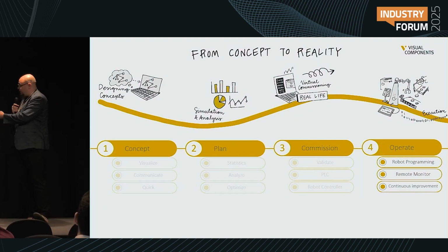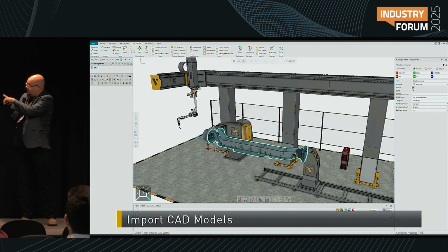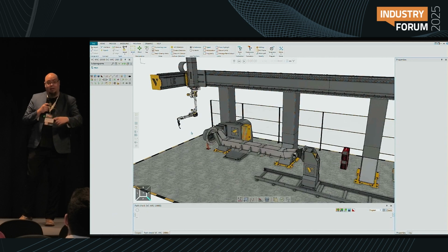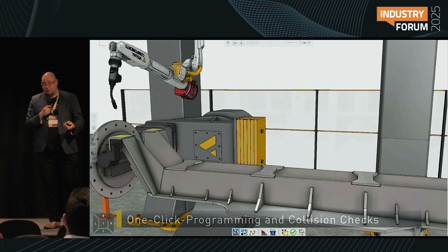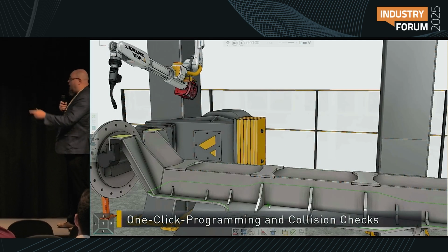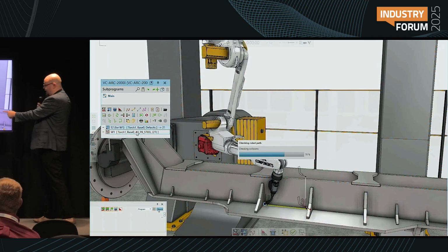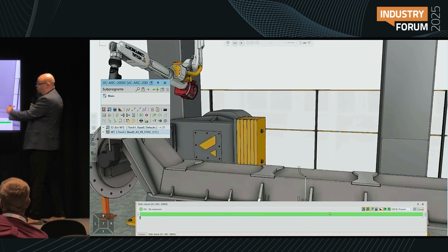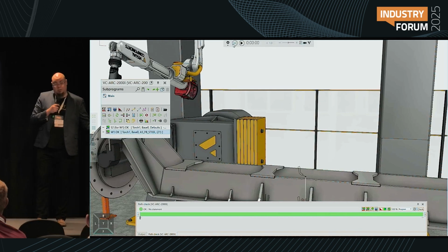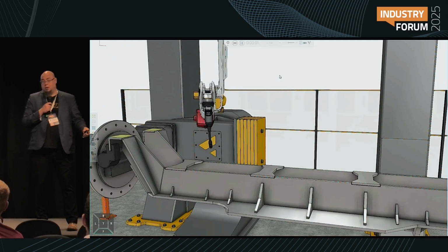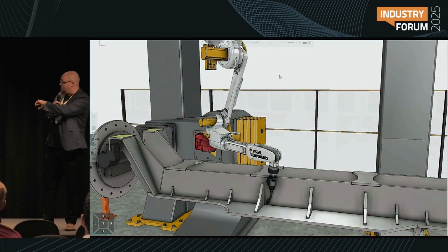So you need to be able, while operating, to teach the robots again and again and again, or change processes and PLCs. While the production is running, during that same day, you should be able to teach, for example, a new welding batch, or a new pick-and-place batch, offline, thus offline programming.